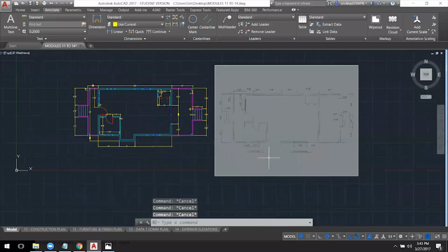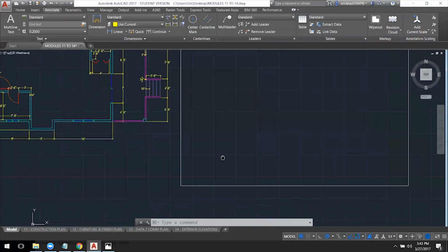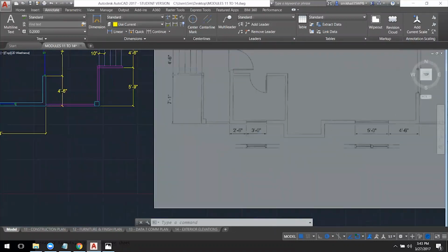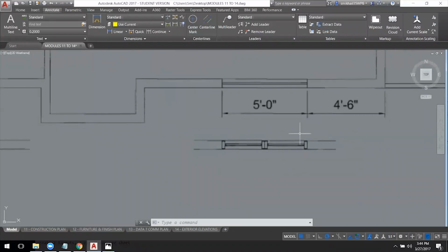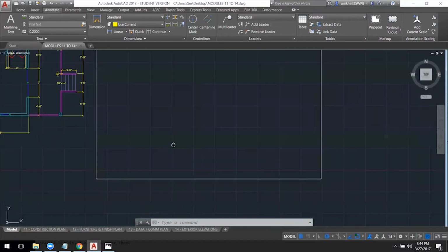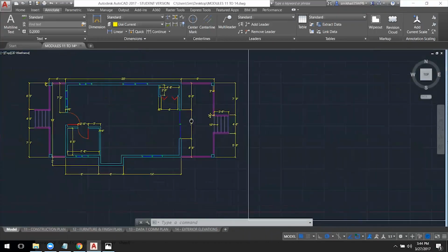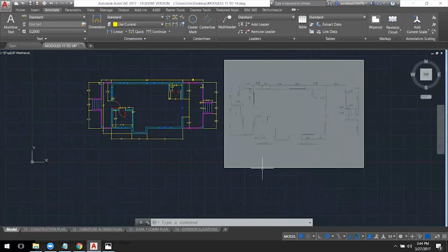We're now ready to get rid of this drawing in here and start working with our line weights. And just for the record, if you zoom in here, there is a little bit more detailed representation of what the window should look like or could look like. This is a swing out window versus the one that we went over in our assignment. It's more of a sliding window. Doesn't really matter which one you've used, as long as you represent it with mullions and glazing, you should be fine for this assignment.